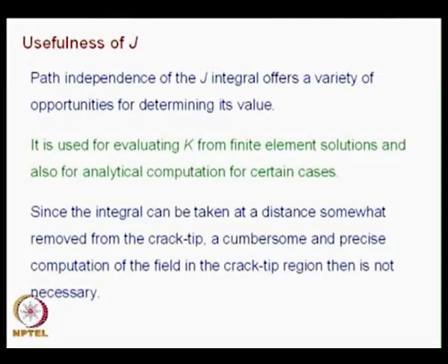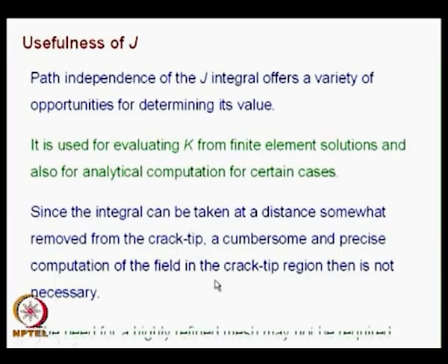in geometry. If you save on a precise mesh closer to the crack tip, you have an enormous amount of saving. You have to view it from that perspective. In practical problems, if you can do away with very precise analysis near the crack tip and yet find out the crack tip parameters, J has been useful, and that is what is summarized here.